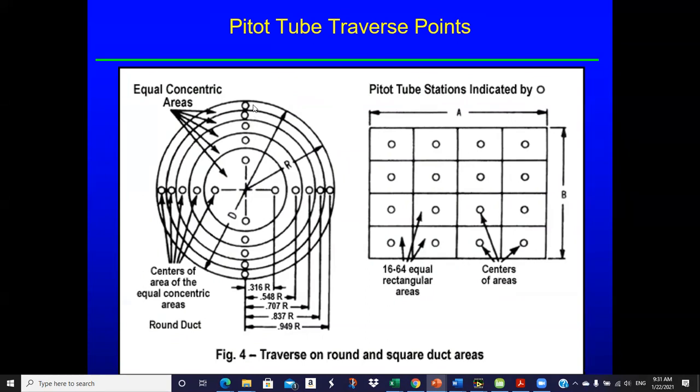Now, if you want to get the most accurate flow measurements, you need to do traverses. And this shows for a round duct, it's really recommended that you do a horizontal and vertical traverse because this is most likely going to be turbulent flow, and there's no telling what the distribution is really going to look like at the plane that you decide to take these measurements. You want to get downstream where all this has kind of calmed out and you've got a fairly predictable velocity profile, but it's tough finding the perfect spot out there in a plant.